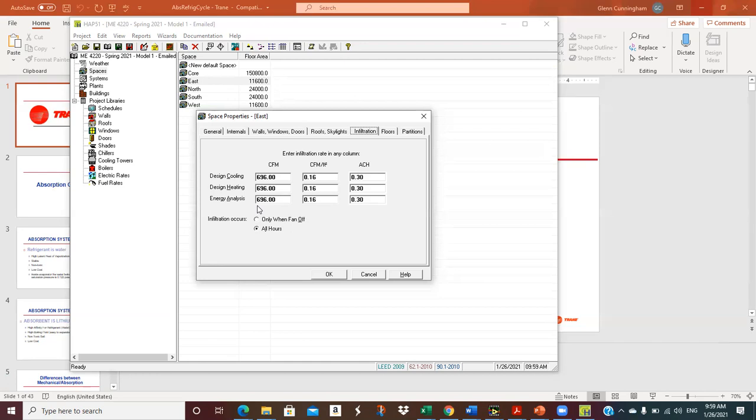Based on the speed of the blower, they know how much air it's putting out because they've calibrated that. So if the pressure is stable, what's being blown in is what's leaking out of the building. So you can measure it in an existing building, but the poor old design engineer is trying to estimate it on a building that hasn't been built.